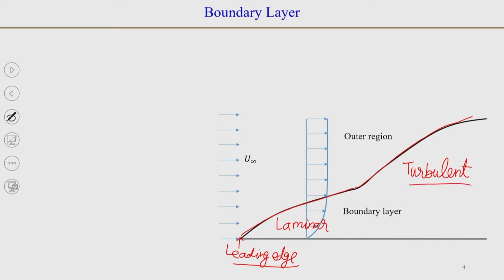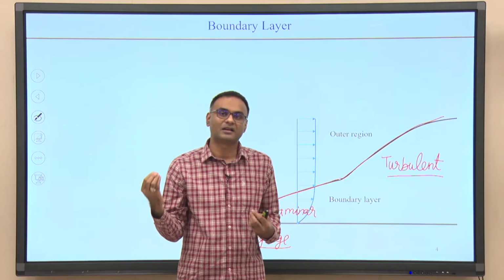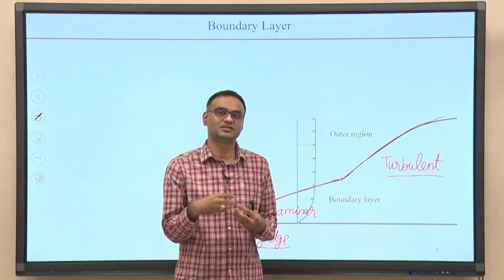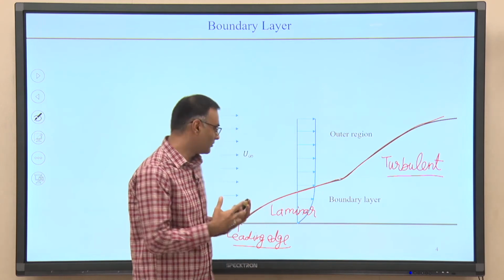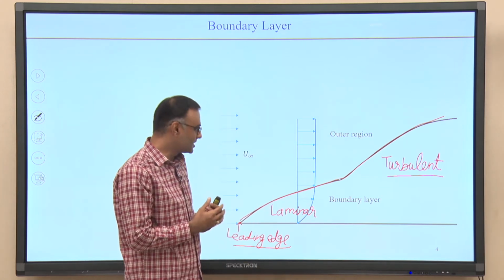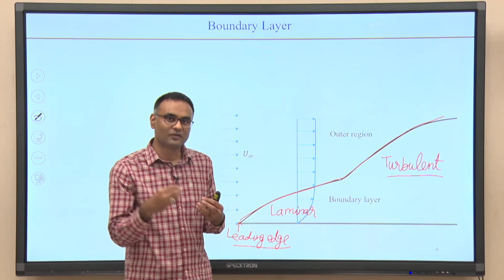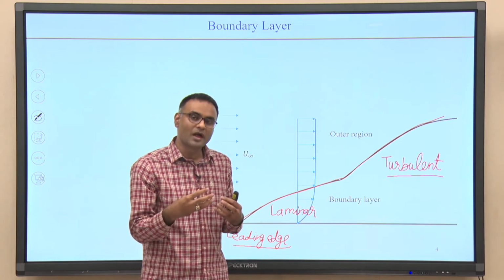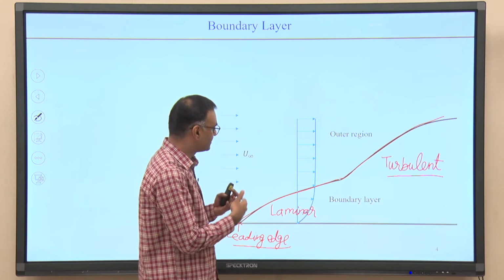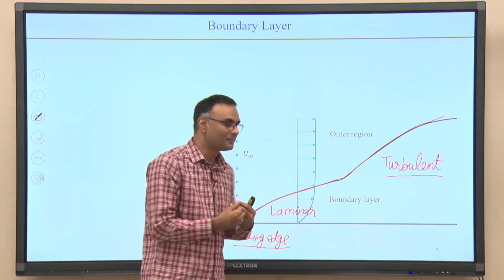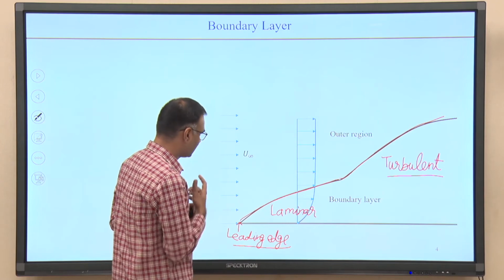The flow becomes turbulent when there are disturbances that cannot be dissipated by viscous effects; these disturbances grow and become unstable, and then there is a lot of randomness and chaotic behavior in the flow.